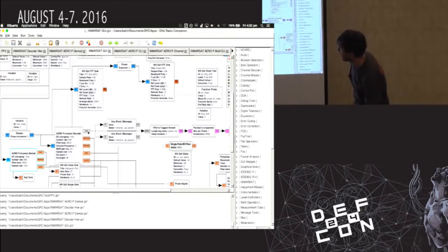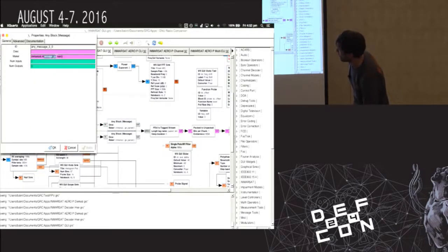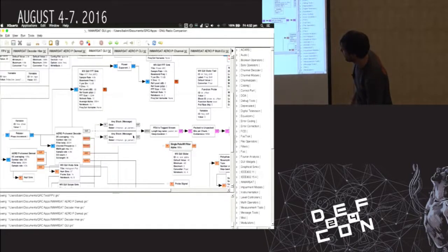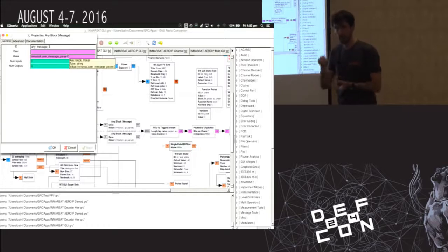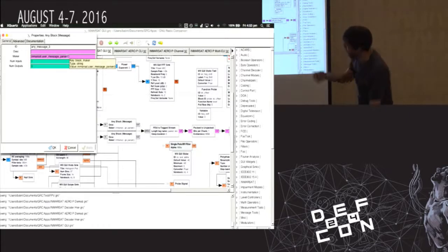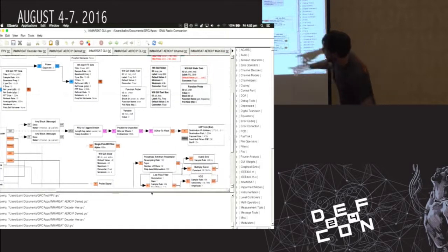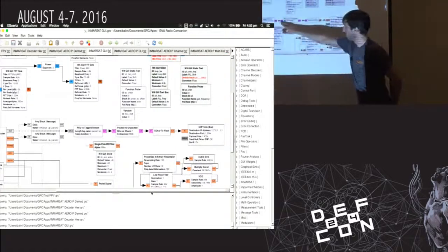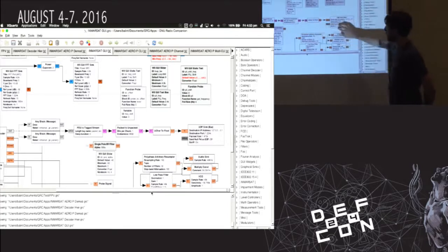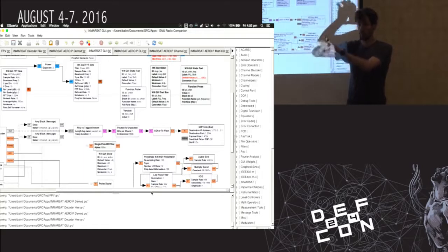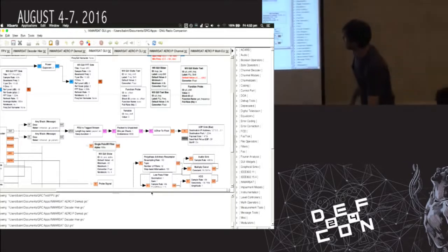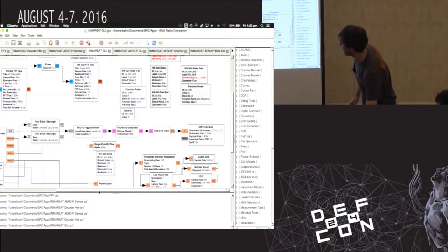So the output, remember, we're getting messages. And here we've got these 2 blocks. One of them is the message parser, so it's just going to tell you all the messages that are coming in. And the other one is this user message parser, which will specifically look for those user messages and then accumulate the data and then print out the payloads. And then in addition, I go PDU back to a stream, unpack those bytes to bits, and then send it out on a UDP sink, because then there's another little flow graph that you can run that will do the raster plot for you, so we can see what the structure of the data actually looks like.